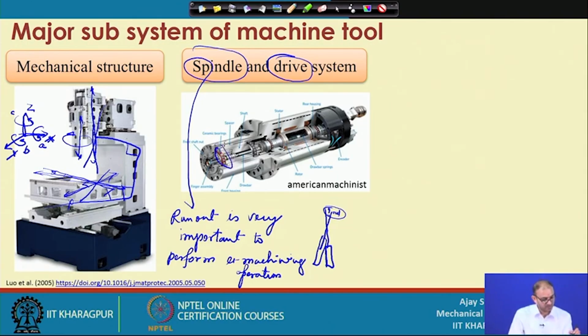Bearings are important, which type of bearings you are putting and how many bearings you are putting, right. The stiffness is directly connected with these, because our tool is experiencing two forces. When it is going into the material, it gets a normal force, and then when you are moving in this direction, it will get a tangential force, and your coupling is here at this location.